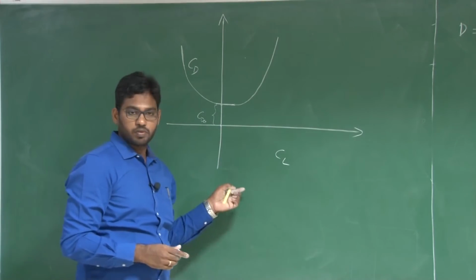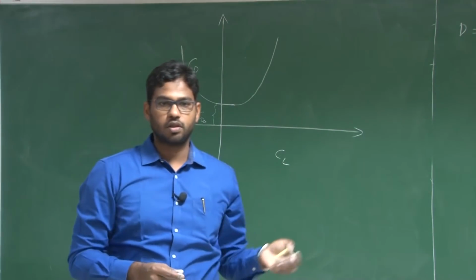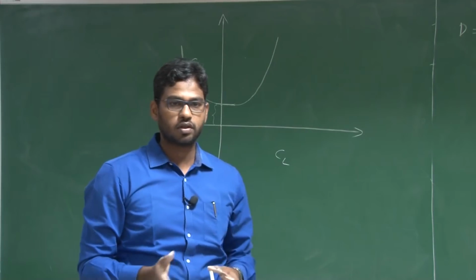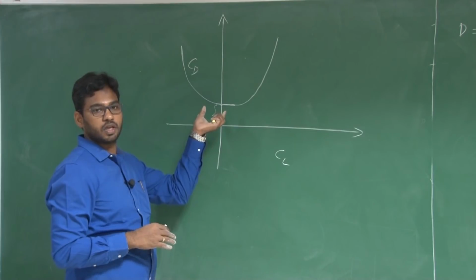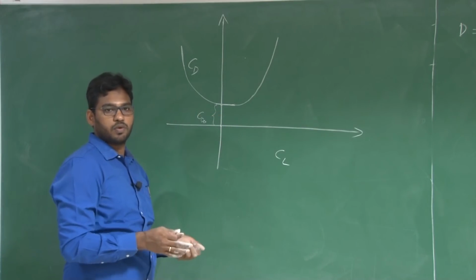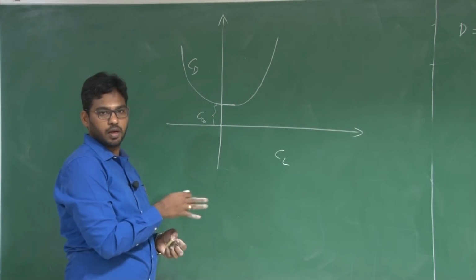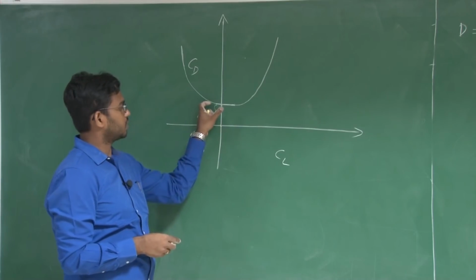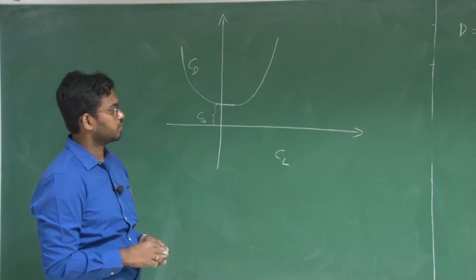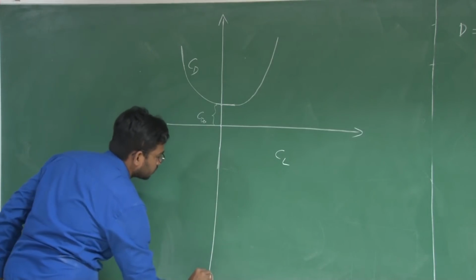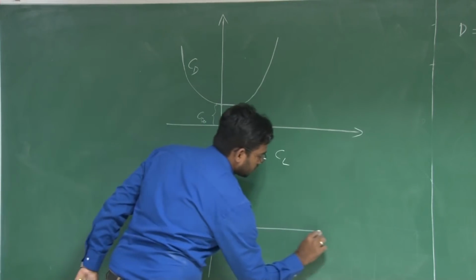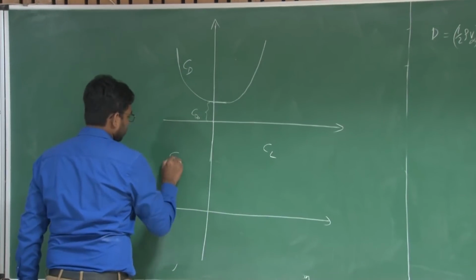Since we mentioned the drag bucket, it is worth discussing various series of aerofoils. It may not exist explicitly for all aerofoils, but there are some aerofoils called laminar series aerofoils where you can see such a drag bucket. And let us see how CD varies with angle of attack.